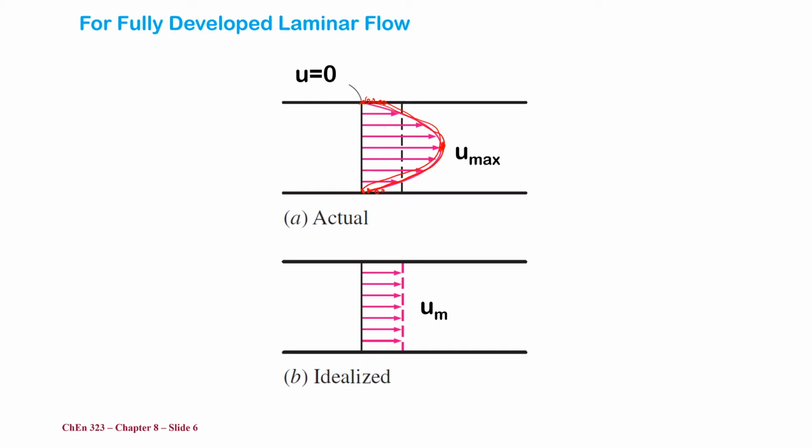But the analysis with this kind of variable, let's say if this is r, the radius, with velocity varying with radius, is going to be a very complicated analysis. So we tend to approximate this velocity profile with an average. So we average it across this cross-sectional area and divide by the cross-sectional area. This gives us the mean velocity. This is the idealized situation. This is how we are going to assume the flow is behaving when we are deriving the convective heat transfer coefficient for internal flow.